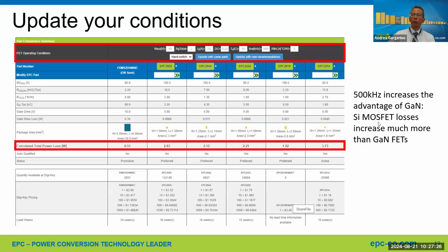What can it do for the rest of the system? And that's really where the why GaN starts, is by asking that question, what can this increase in switching frequency provide? Now, you can also look at what can the lower losses provide, what can that package area provide, but it's kind of all driven by this ability to switch fast and increase the switching frequency of the application, right?